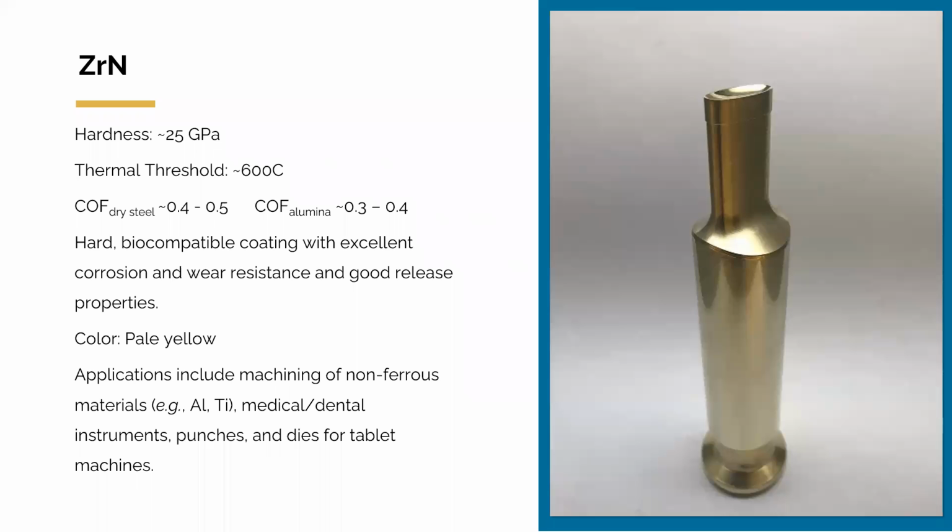All right, it's not that it's going to be much higher performance in many applications, but in some applications it is superior. So in the case of consumer products, where you have constant exposure to water, or salt spray if you're close to the ocean or something like that, the zirconium is going to perform better than the titanium. In this case, zirconium nitride is on a tool here. It's a punch that's used in the pharmaceutical industry, for instance.